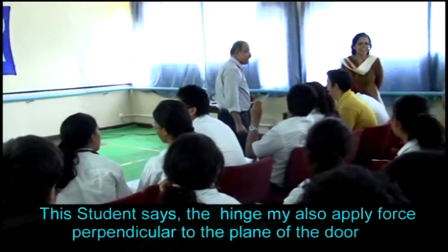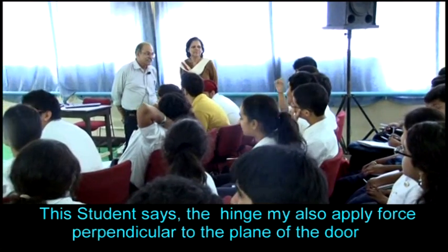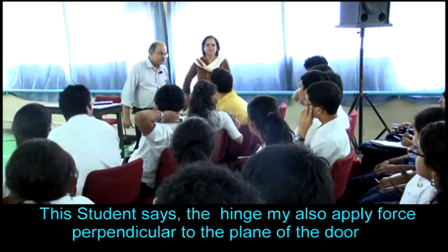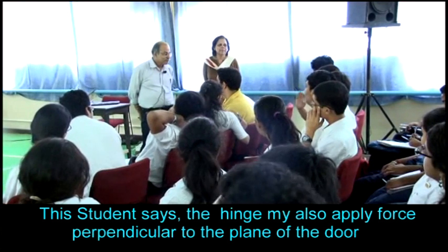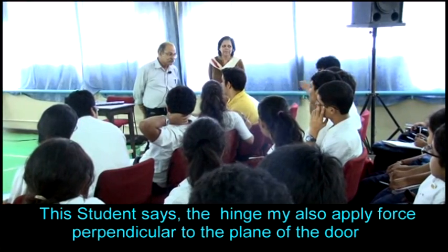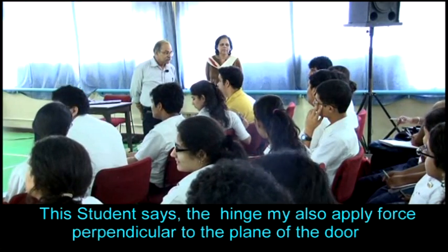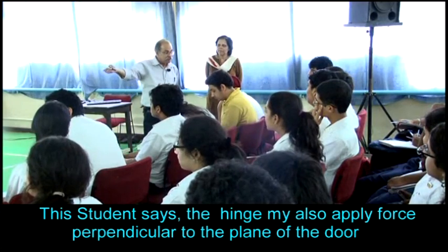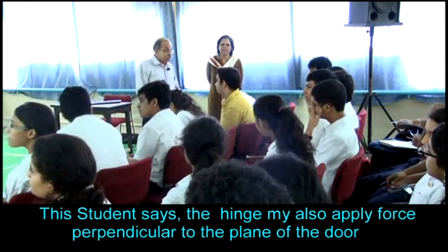There is a force that the hinges will exert on the door because the door is upright and standing, but that force is 0 because the angle is in the same plane, which is why the door is in equilibrium, because even if you forget the reaction force, the total action on the door will be 0 because that theta is 0. Yeah. But the hinges will still exert that horizontal component, forces by the hinges on the door but in the other plane also, so won't they be perpendicular? Okay. Then the same question will be there. Who is balancing that? You are adding to your complications.